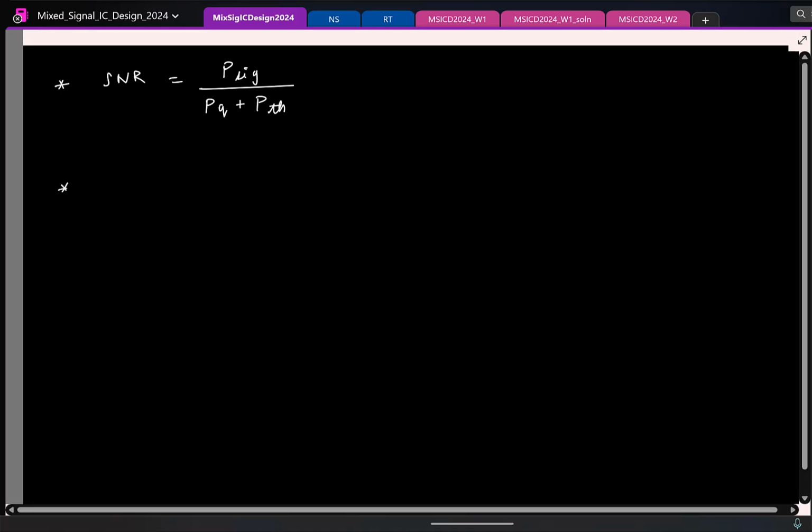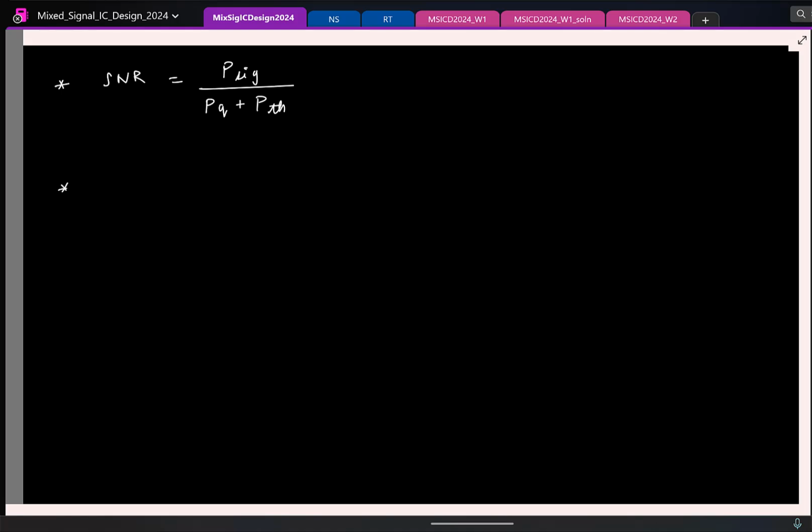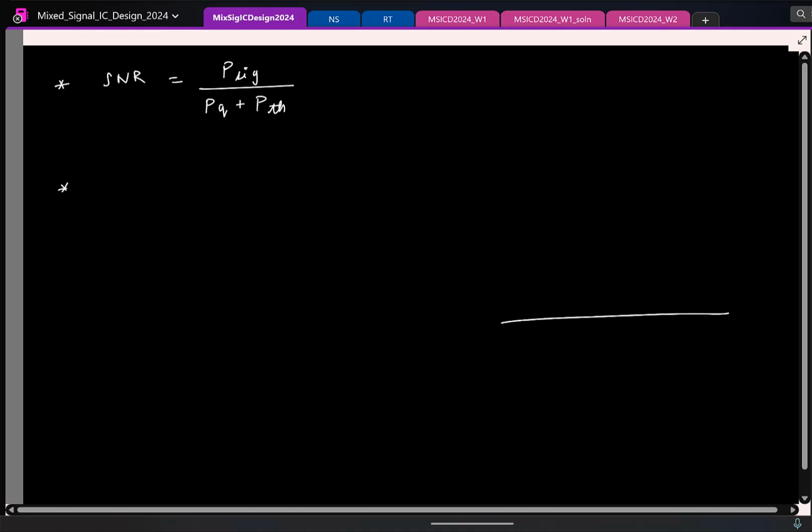So in addition to this, it turns out we'll be making these ADCs using transistors. A transistor is a linear device or a non-linear device? Non-linear. So if you make a circuit or a system with a transistor, will that be a linear system or a non-linear system? Non-linear system. So if you don't design it properly, you will also have severe non-linearity. So if I apply a sinusoid, ideally, as of now, we expect to see the sinusoid at the output spectrum and a flat portion corresponding to quantization noise, thermal noise.